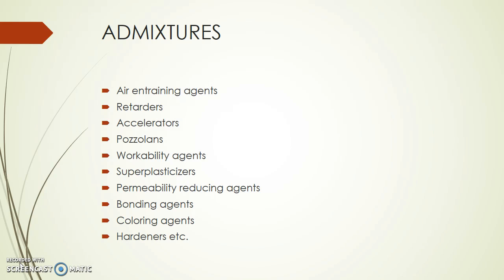The most important is the air entraining agents. As I said, they improve the durability, reduce the damage due to freeze and thaw, and improve the workability and the water tightness. So they're very important.